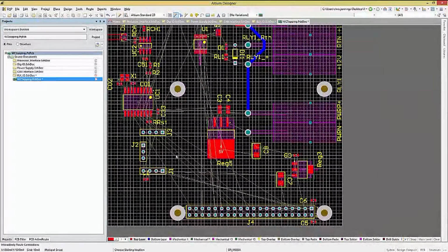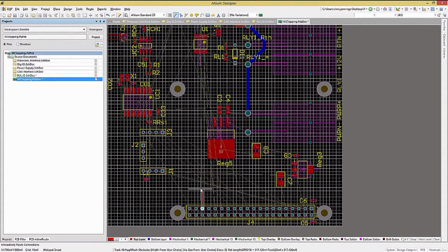Now we can place the wire segment endpoints by clicking at the desired locations using the left mouse button. When the route is completed, right-click once to finish this route. To exit routing mode, right-click again.